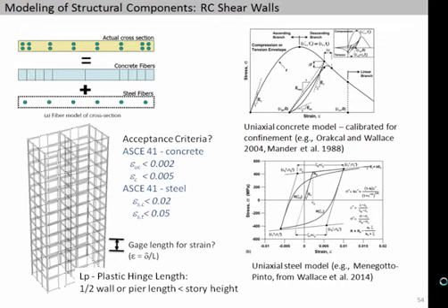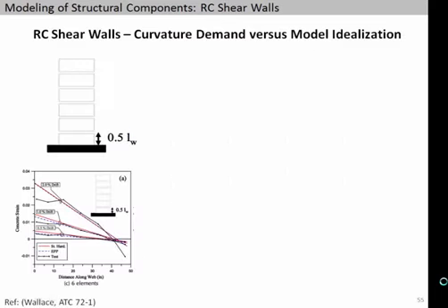Typically, if we're thinking of a plastic hinge in a wall, we want to think of that gauge length as being roughly the plastic hinge dimension, because that's the one against which we compare our acceptance criteria. Locally, there may be much higher strains than that, but in terms of what we could compare to based on tests, we have to have a common gauge length assumption.